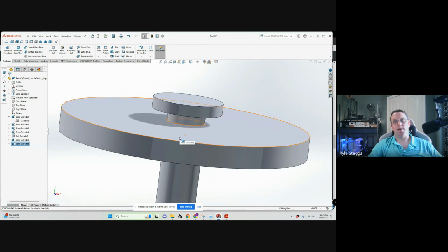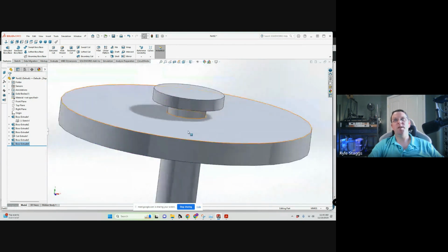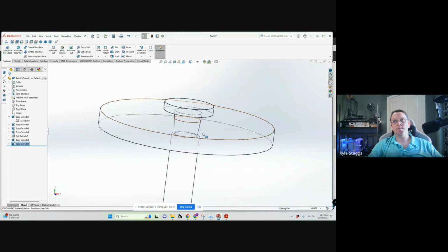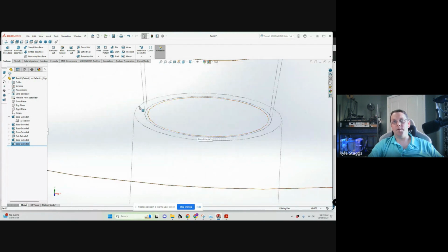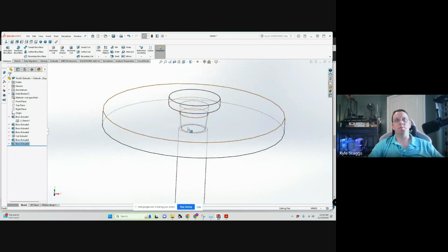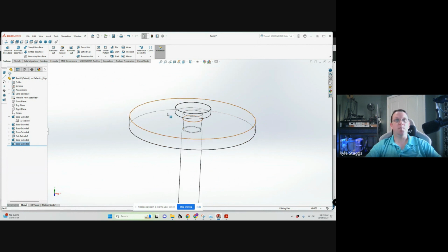And that way you have just a little bit of overlap in the material. So if I switch to wireframe, you have just a little bit of overlap in the material, not a lot. You want to have one line of print material, so 0.1, 0.15 millimeter between these two. But that'll give you a print in place roller design. So this started out as a print in place roller design, and then worked a little bit easier. You can also round them, which I highly recommend.